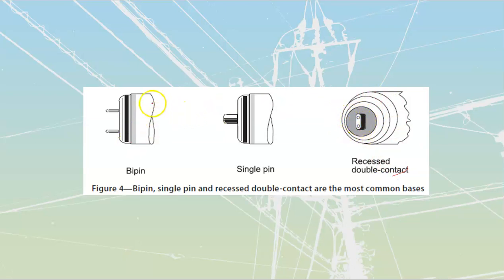A bit more reliable than the bipin. I think everybody by now has broken one or two of these, where you're twisting them in and you snap off one of those pins, or it doesn't align with the tombstone. They can just be frustrating, particularly on low-quality troffer fixtures where the ends are sometimes even a bit misaligned.